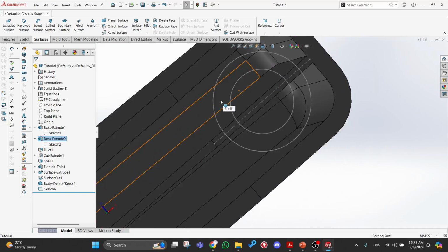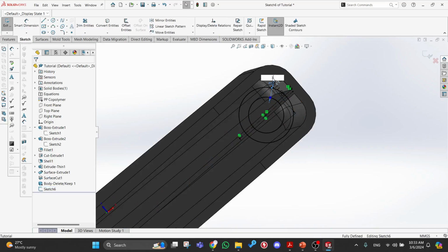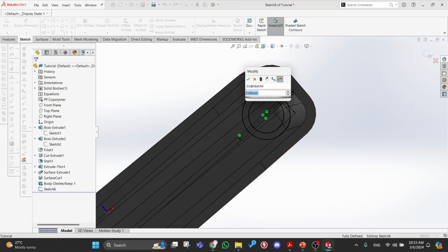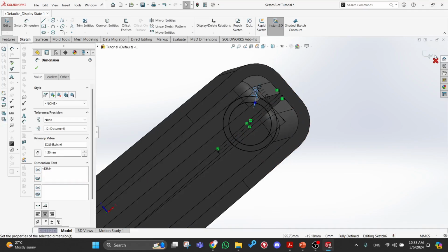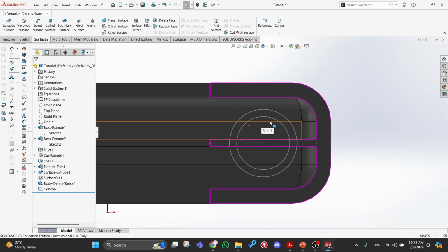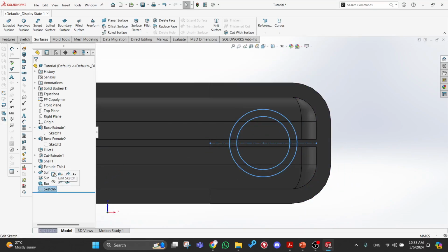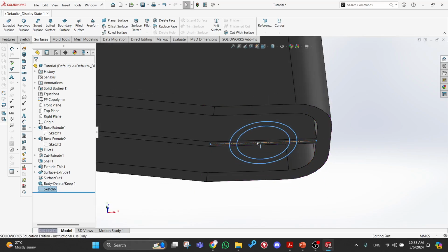Here, no issue here. Actually, this one can just be ribs, right? We don't have to make it too thick. Yeah, let's just make it a rib. 1.5. Why do you need it to be so thick anyways? Doesn't make any sense. Because I'm scared I will have thin steel here if I make it that.